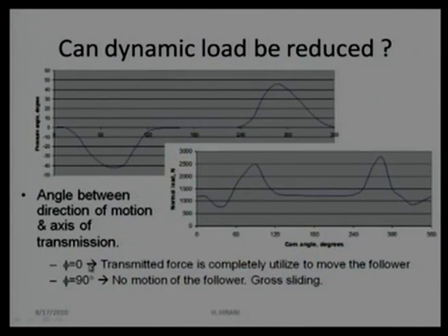But we know the path motion, and because of the variation in motion, there will always be some pressure angle. If we go for a better design with a larger radius, this pressure angle can be reduced, but it will occupy more space, and space constraint will always be there. It is going to increase the size of the machine. So, we will always look for a lower size machine. So, there will always be a trade off.